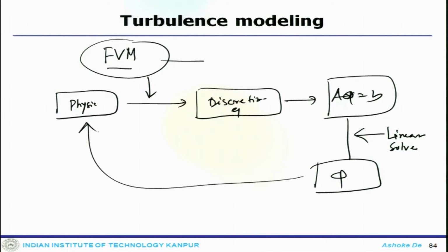So, the global picture we started with, if you close it down: you have a physical problem of interest in hand, you apply your numerical technique, the one we have discussed here is the finite volume, and you get a discretized equation that leads to a linear system. Then we discussed different kinds of linear solvers, like iterative and direct solvers, which get you the solution.